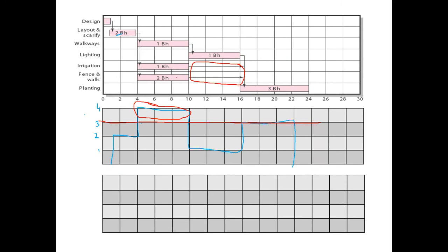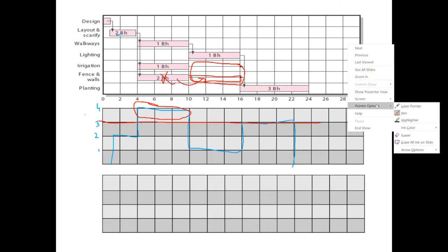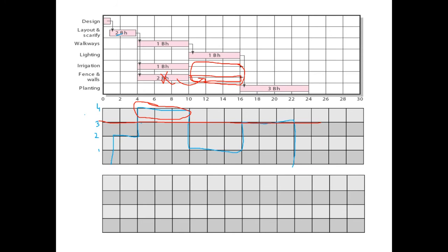So I think the suggestion could be that if we move, for instance, this activity here, we could have a very nice looking smooth resource profile. If we do that, let's move this activity from here to here. Let's make use of this time. So if we do that, my new resource profile would look like this, and then over here it will be reduced to 2.